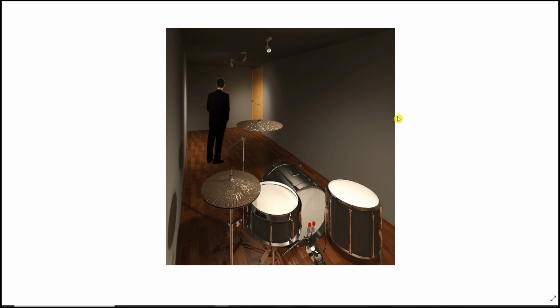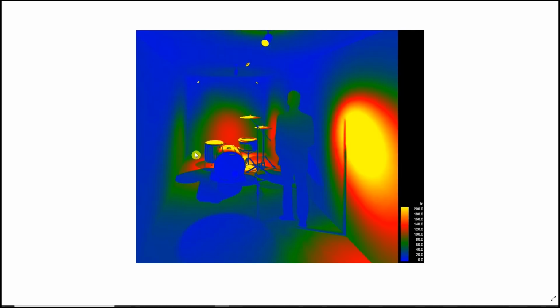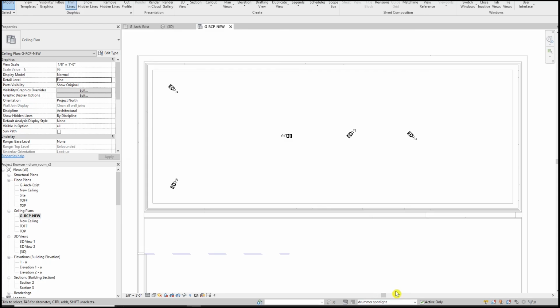It's a little less clinical than the big linear fixtures. It adds a little ambiance, and there is some flexibility here, obviously, in any of the track lighting arrangements. Heads can be rotated or moved. As you've seen, by aiming things around, you do get a little bit more spill. This is your central area over by the drummer. And wherever these other track lights aim, they're going to be nailing some high illuminance, and then there are some dark spots where you fall into the shadows in some of those areas. So that's a list of different things that I looked at.